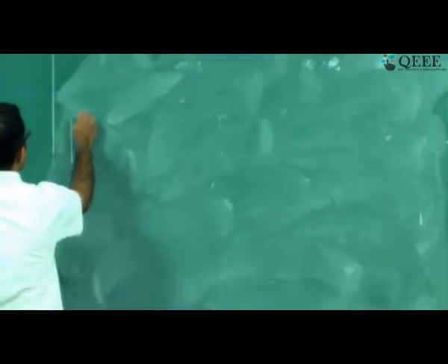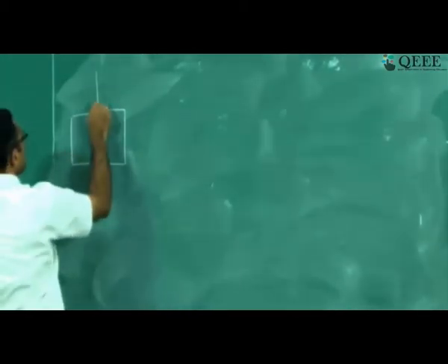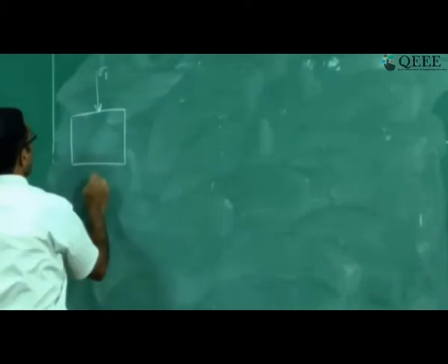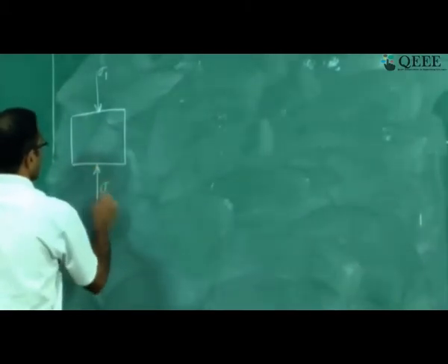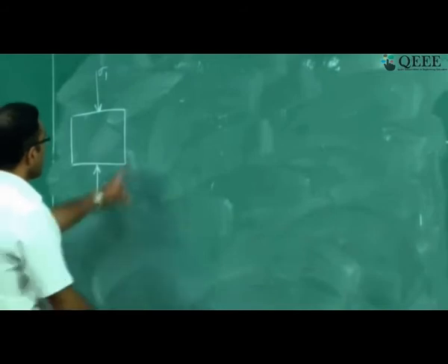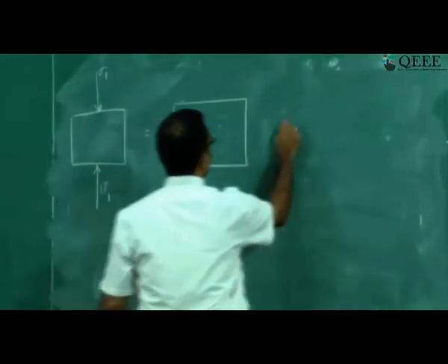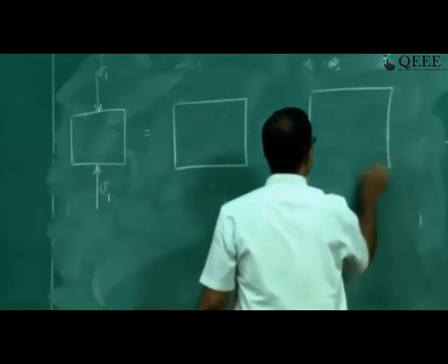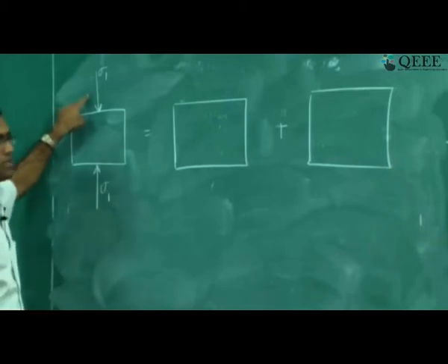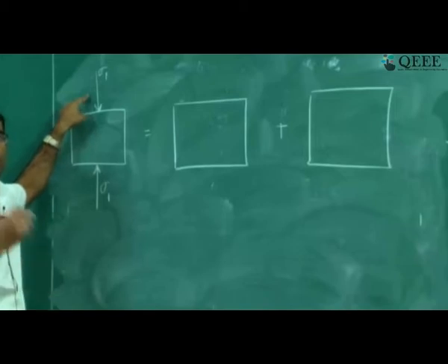If you take a small infinitesimal element which is subjected to, say, uniaxial compression, sigma 1, and I want to split this into the hydrostatic part and the deviatoric part, it's the same element. As far as this infinitesimal cube is concerned, the shear stresses are all 0 and of the normal stresses only sigma 1 is there; sigma 2 and sigma 3 are 0.